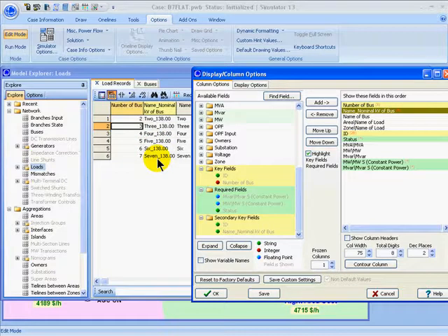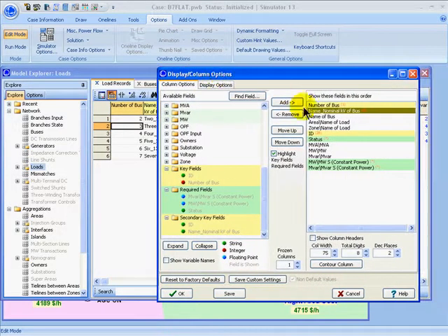In other words, you could have in your case 2 bus 2s with the text TWO as the name and nominal kV of 138. Simulator would not prevent you from doing that, nor would other PowerFlow packages. Basically the number is the only thing that's strictly unique, but the name could be used as an alternate way, again, of matching things up, like one-line objects or things from an auxiliary file from an old case that you want to transfer to a new case where the bus numbering may have changed.